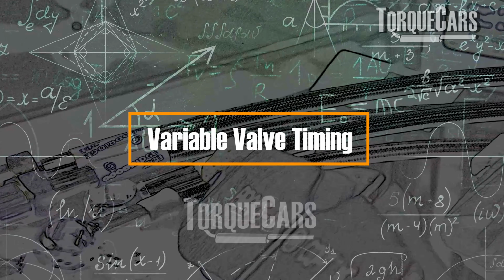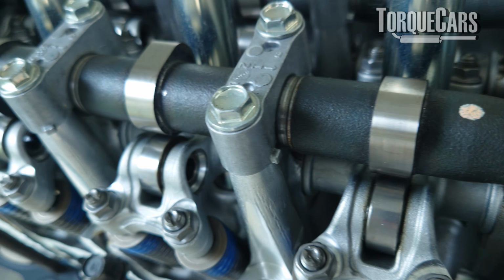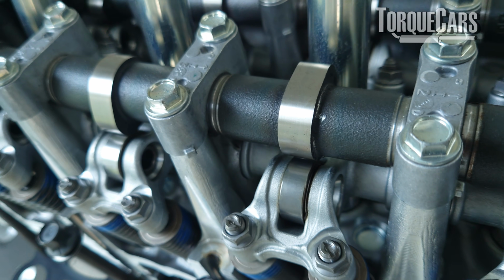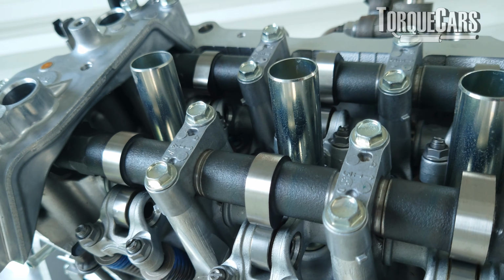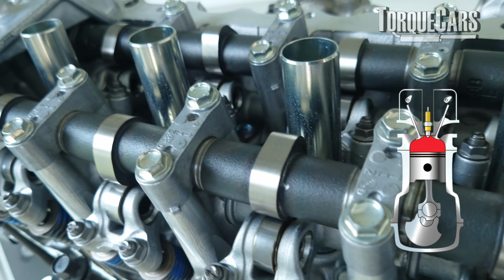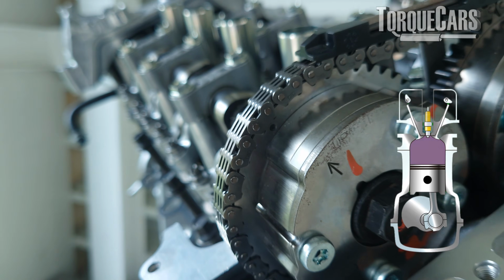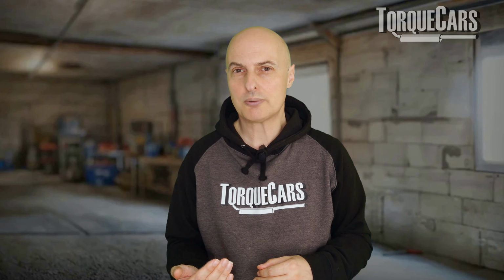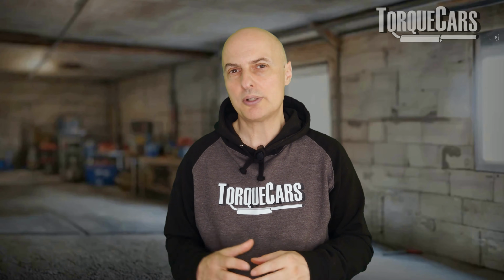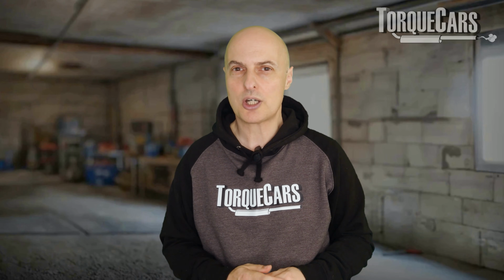Variable valve timing. Your modern engine is able to control the opening and the closing of the valves. The cam does this job, but variable valve timing takes it to the next degree. Depending on whether we're operating under load, the engine is producing a lot of power, or you need the fuel economy, it can trim the opening and closing of the valves accordingly. If there's a malfunction in the variable valve timing system, that can cause this problem on acceleration. The valves are staying open or closed for too long a duration, and that means we're going to be down on power.